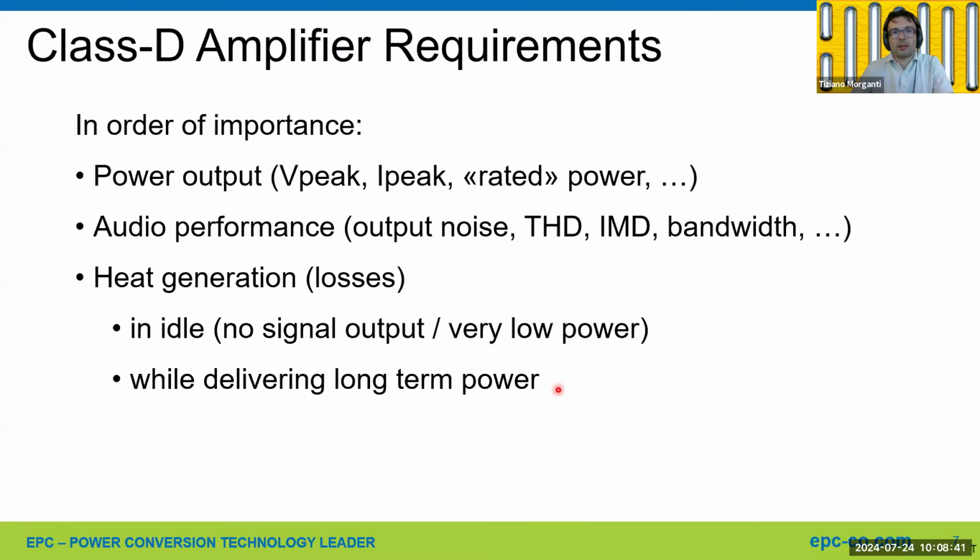Basically, those are usually limited by the power dissipation. If you can reduce the long-term power losses, you can also reduce the size and the cost of the heatsink. Another requirement is the total size of the solution, in terms of the usage of PCB space and the height of the solution. Especially in high channel count designs, this is also an important factor to consider.